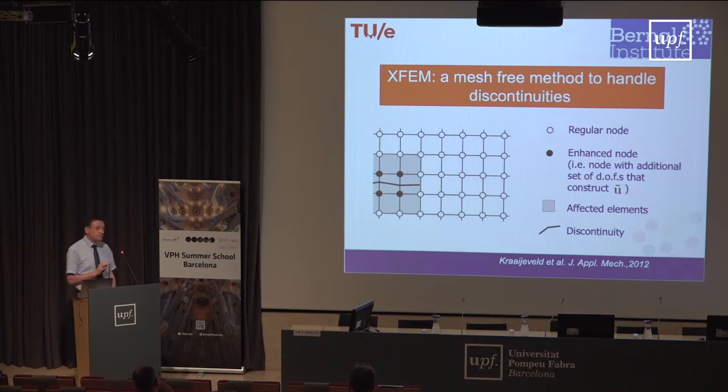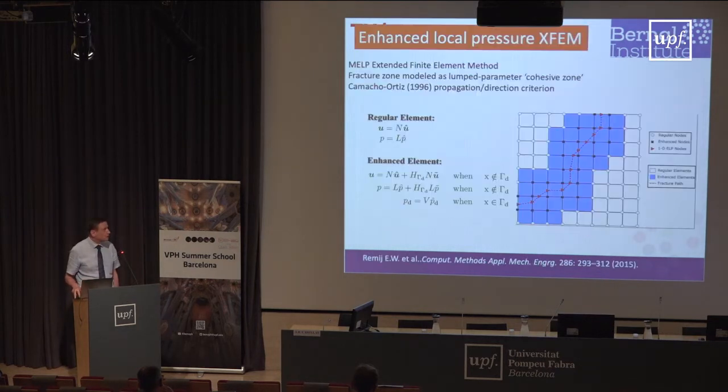And the nice thing about XFEM is you don't need to do remeshing. You just enrich nodes. As you propagate through the mesh, you progressively enrich nodes as you go through the finite element analysis. And so at some point you get a whole path followed by the finite element method and progressive enrichment of all the nodes which are tainted in black here.